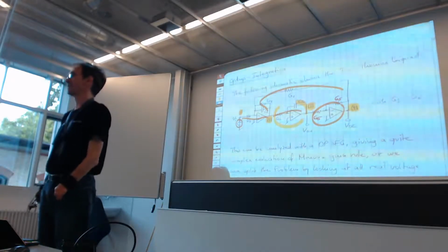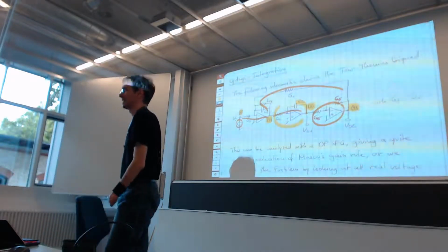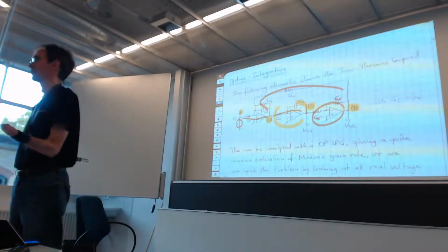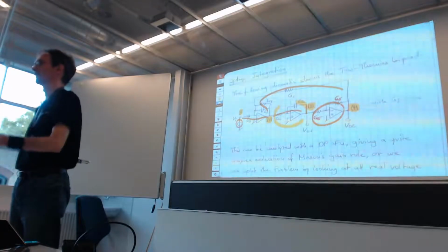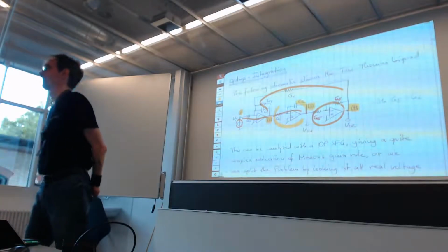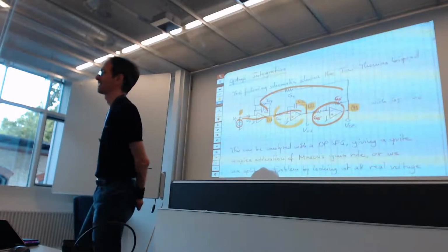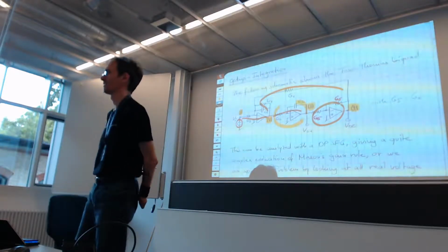On the PCB, if linearity is not an issue, but speed is, you can also build the first one because you can buy an integrated circuit which gives you transconductance. We will later see some of them here. I will introduce you to the AD844 and the OPA860 with which you can do crazy and very fast things on the PCB.